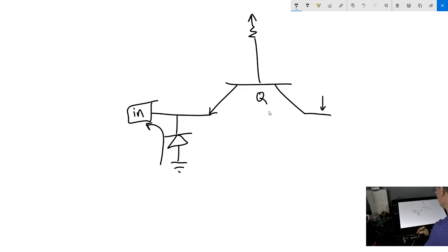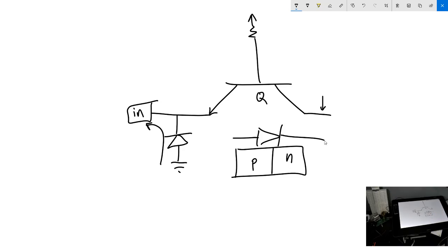And then of course, because the diode is destroyed, everything else gets destroyed too. But anyway, this does protect against small negative voltages and low current negative connections. So a diode is just a P next to an N, right? And it's basically like this. And it's easy to remember which is which, because P stands for positive, and typically you put the positive voltage on here, and N stands for negative. So, that's how you would normally forward bias a diode.